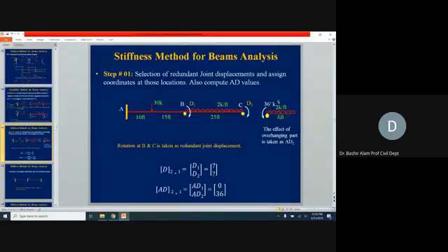2 multiplied by 6 gives you the equivalent resultant point load, and its moment arm is 6 divided by 2. So 2 times 6 divided by 2 comes to 36. Its equivalent moment we will put here at joint C. How much will be the shear because of this overhang 2 kip per foot load? It will be 2 times 6, which is 12 kip.